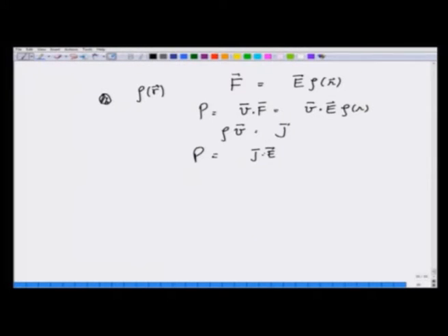Another way to look at it is, if I have a wire, if I take a very small element in this, then the power in this is going to be V times I. This is joule heating, and V is nothing but E times this small length L. I is nothing but J times A, and you can write this as E J delta L A. This is nothing but that small volume.